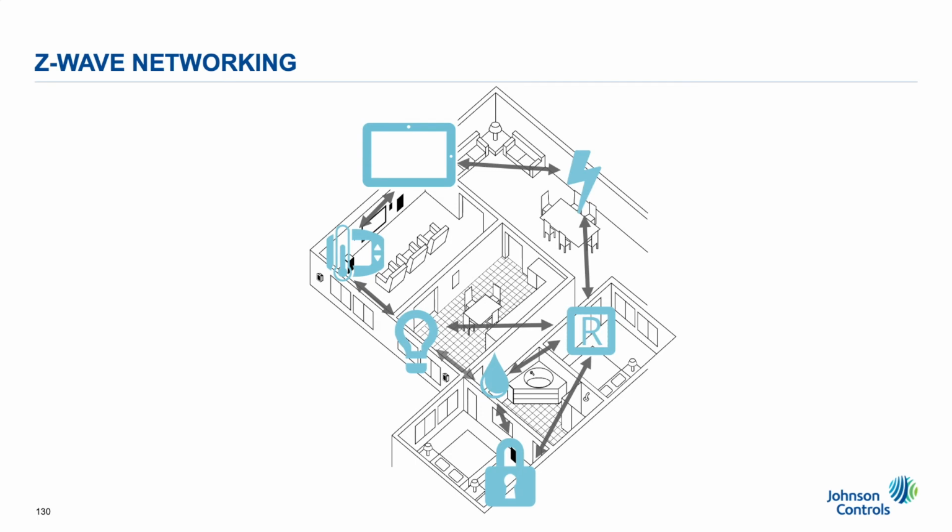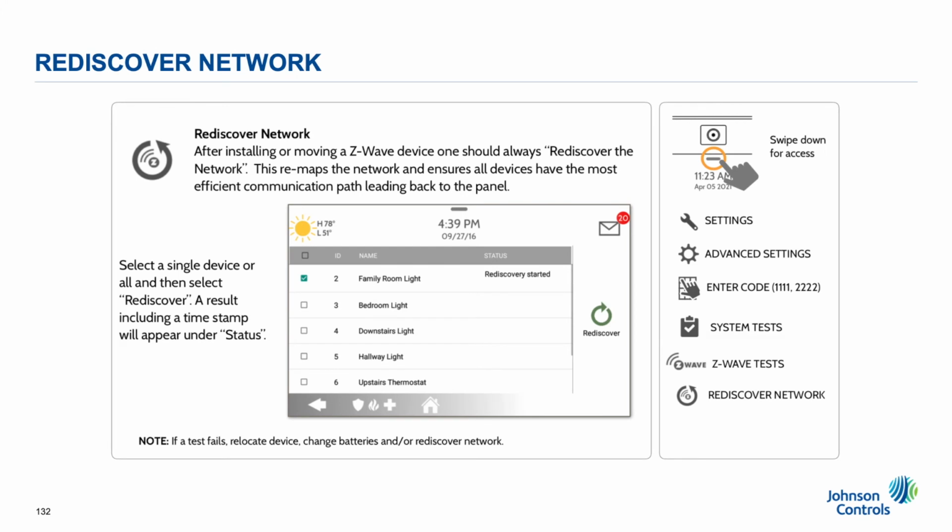Rediscover network. This is a very important tool that should be used after adding Z-Wave devices to the panel. This is what maps the mesh network and creates an efficient route for devices. This tool should also be used whenever devices are added, deleted, or moved.